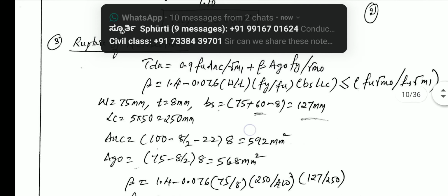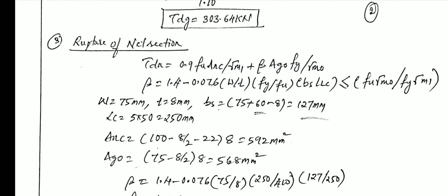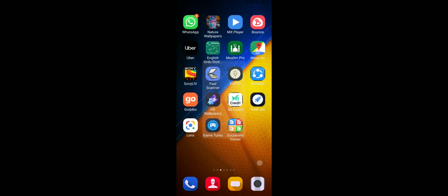or you can note it down directly from the code book. So from the steel table you get it. How you get the steel table, I'll just show you. In the steel table, when you refer to IS, in this table they give the recommended gauge distance in leg for angles. In the diagram they give two values, A and B, for two bolts. For a single row of rivets or bolts, they give the value here. 100 mm is the leg. If it is two bolted, 40 and 60, 40 they give. If it is only a single bolt, the G value is given as 60. This table you have to refer.